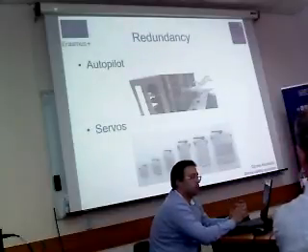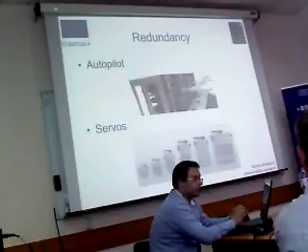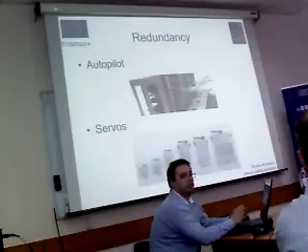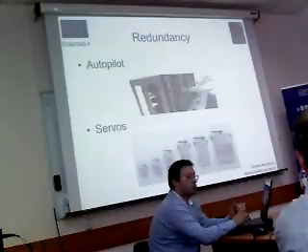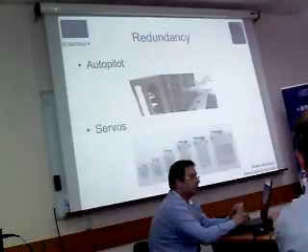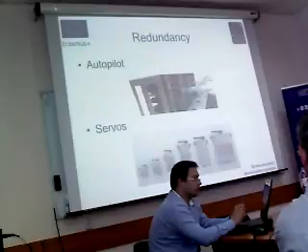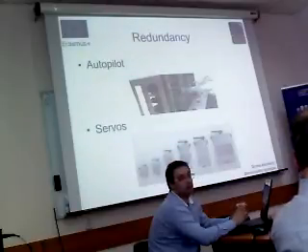So these modules include logic for monitoring the operational status of the electronic components. And in the case of failure in one of the autopilot flight controllers, it changes to another module. At the same time, the system notifies the operator and executes, for example, a scheduled fail-safe or fail-operational process. So all this must be executed in a split second, because in case of an error, even just a few seconds could be fatal for the device.